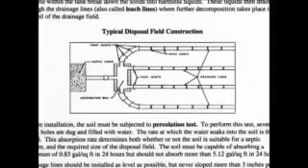The next main item there is the distribution box, and that distributes the water into, in this particular case, 4 what's called leach lines or drainage lines. And those lines allow water to seep through the pipes. The pipes are not porous, but they have open areas in the pipes to allow the water to seep into the field and to be absorbed into the field. Now, note, this is an important item, and let's highlight this. Before installation, the soil must be subjected to a percolation test. In other words, how fast will the water go into the ground?